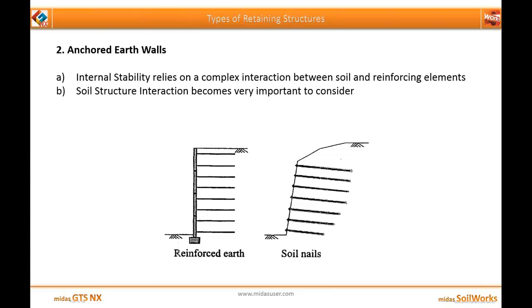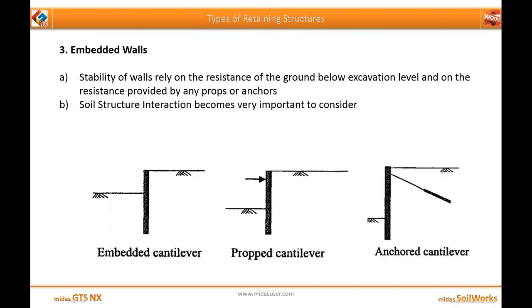Now, the internal stability of this kind of wall relies on a complex interaction between the soil and reinforcing elements. So, soil structure interaction becomes very important to consider and hence one should go for numerical modeling. Now, third is the embedded walls. Now, the stability of the walls relies on the resistance of the ground below the excavation level and on the resistance provided by any props or anchors which are used. Now, the soil structure interaction becomes very important to consider.